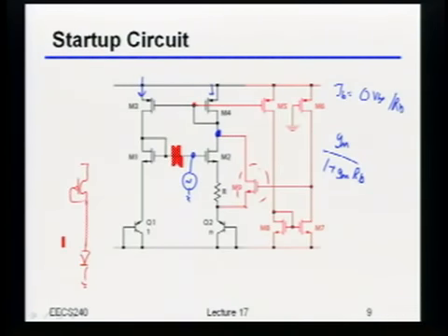Don't worry about ROs, by the way. The emitter resistance. Yeah, there we go. It'd be something like the resistance of the diode, right? What is that resistance, by the way? Is it big or small? Small, right? So we can usually ignore that. How about on this side? Do I have anything making that resistance large? No, right? I just have the diode.